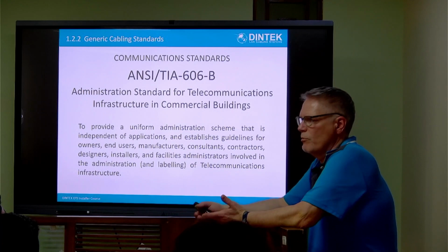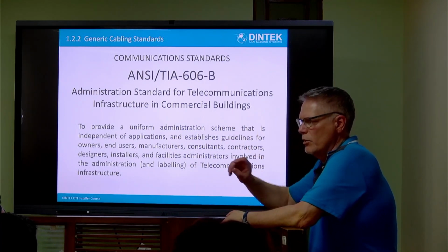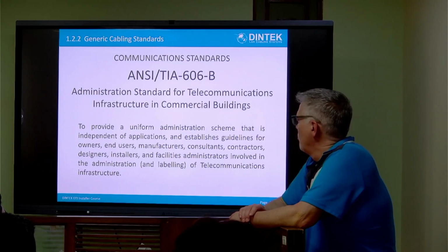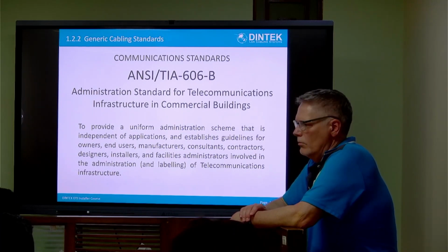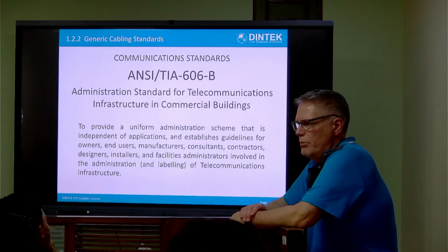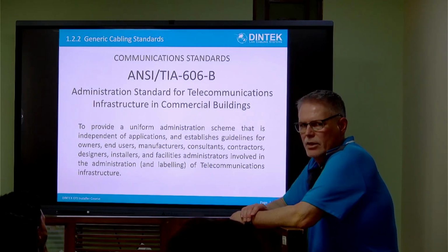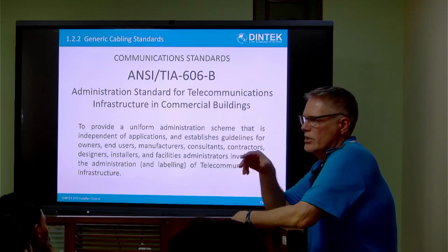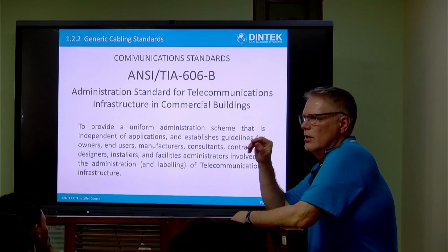Or the customer might say, I want you to number them 1A, 2A, 3A. But when you're dealing with universities or big installations across a wide area with maybe up to 10,000 outlets, you need to start breaking down where cabinets are, where cabling grids are.